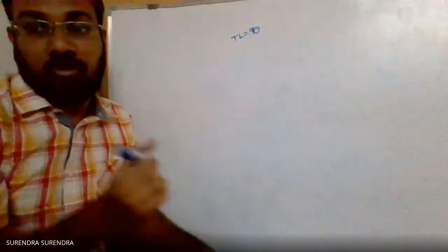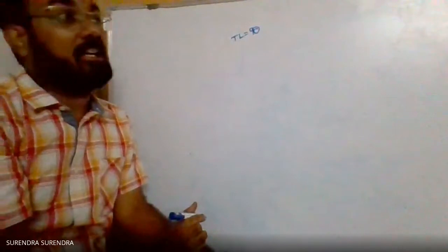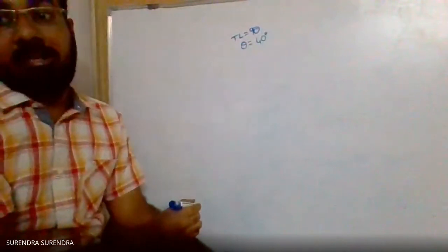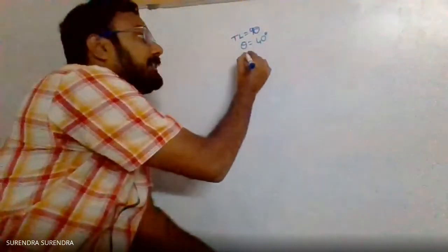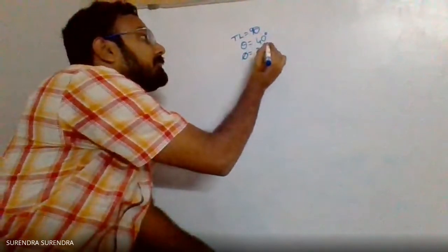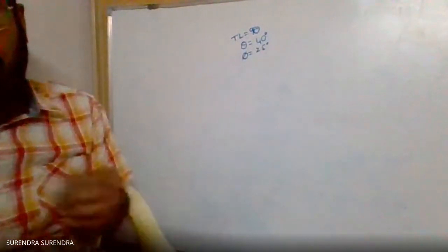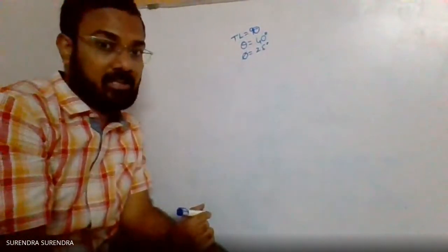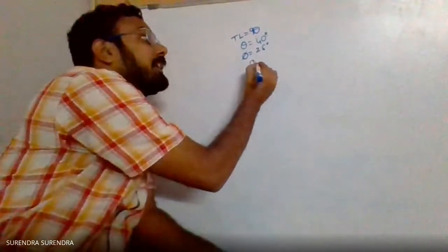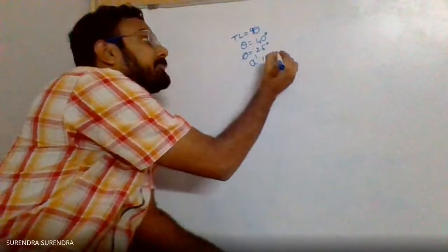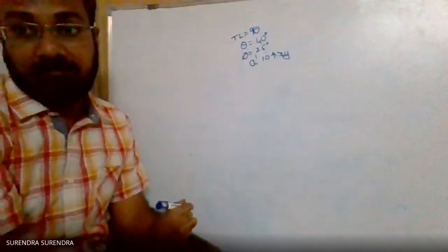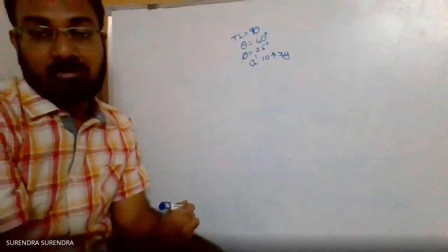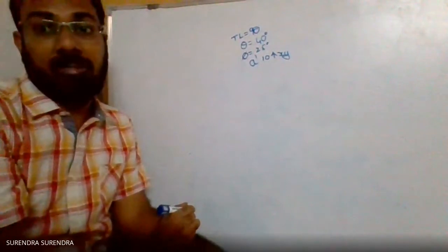is inclined at, it is not 400, it is inclined at 40 degrees to the HP, means theta equal to 40 degrees and 25 degrees to the vertical plane. Phi equal to 25 degrees and end A is 10 mm above the HP. Above the HP means front view location of point A. So A dash is 10 mm above XY line and 25 mm in front of the vertical plane. So vertical plane implies top view location.